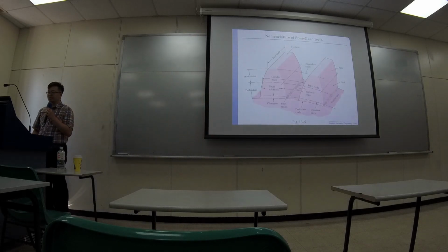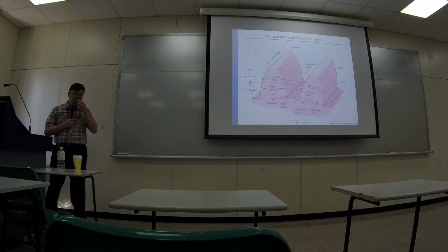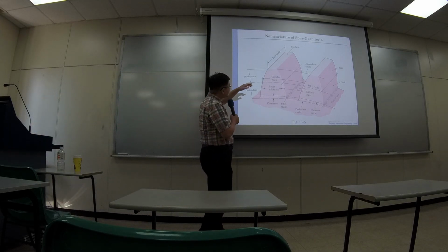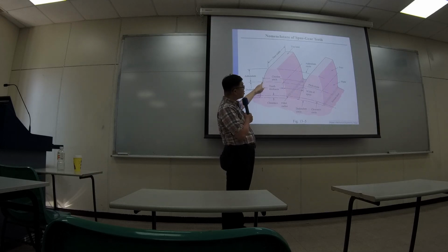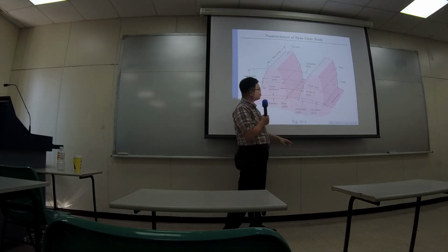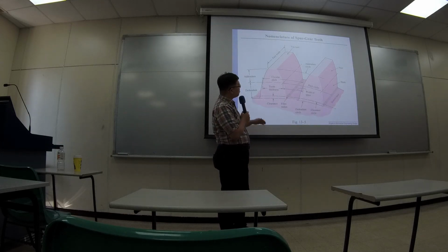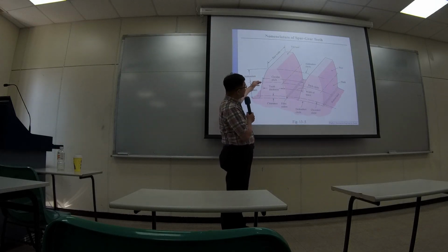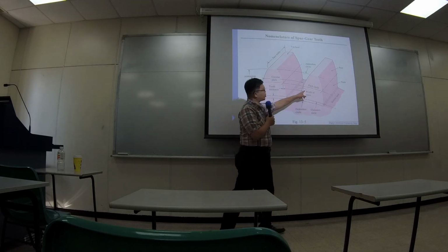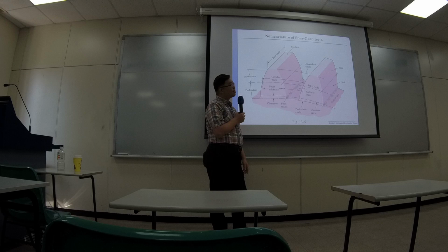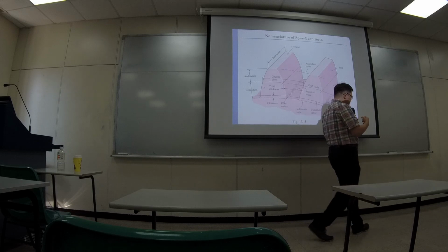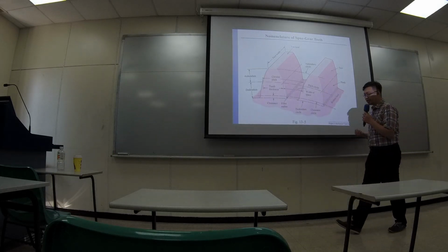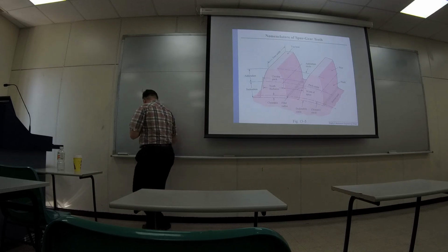Now, there are some names you need to know. The distance from one edge of the teeth to the other one, exact same position, is called a pitch. And usually the pitch is being calculated around a pitch circle. So where is the pitch circle? Pitch circle is like the position where you assume there's interaction of forces.